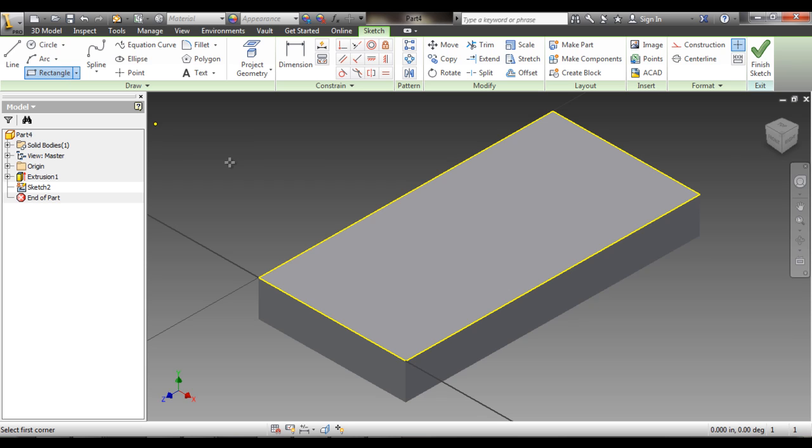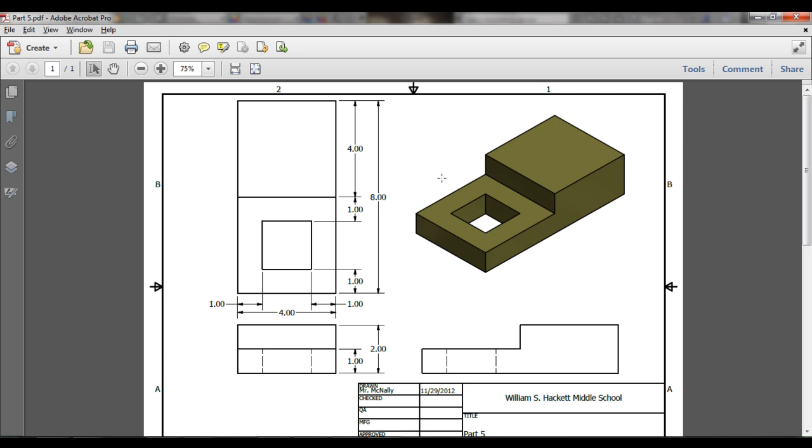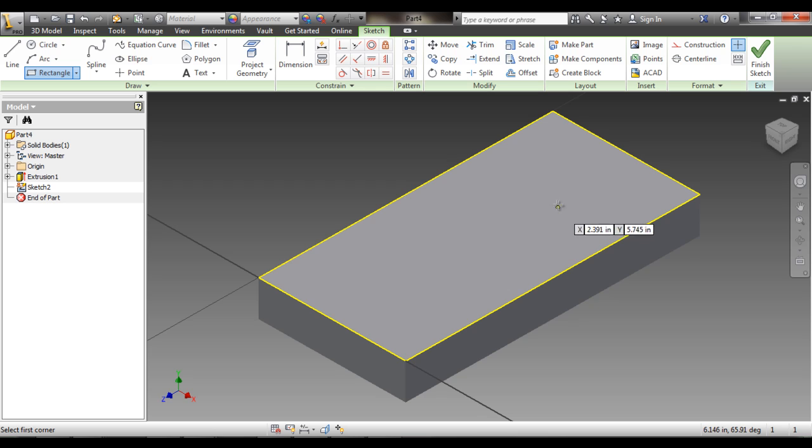So here's a trick. If we know that this rectangle, this really the square, because it'll be 4 inches by 4 inches. If we know that this square is going from the far corner to the very middle of this larger rectangle, this base rectangle, we can just use the snap feature in our rectangle tool. So if we come to this corner, that circle is going to turn green because it's snapping to that corner there, the intersection of those two lines. We'll click once.